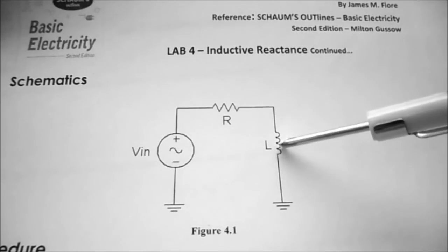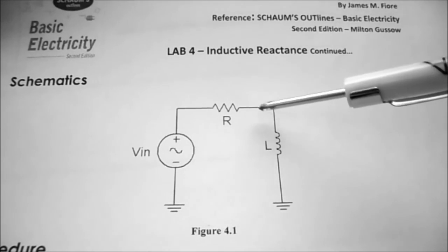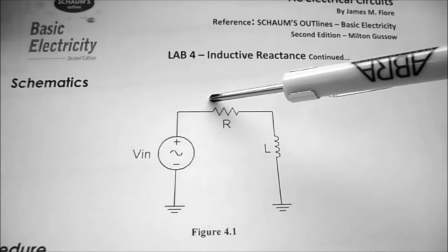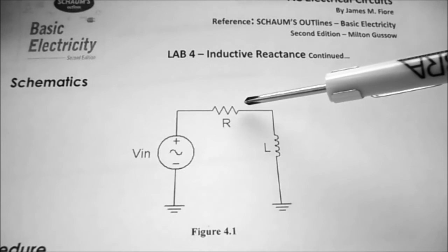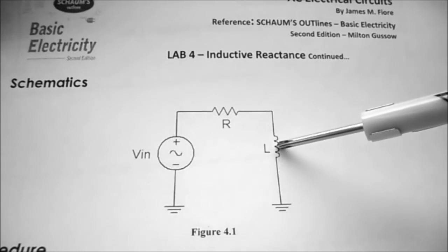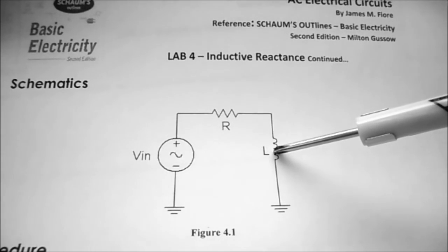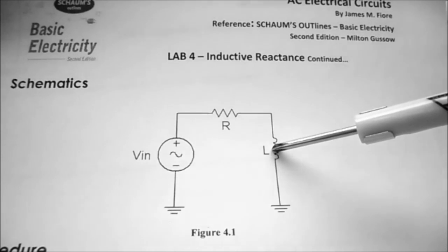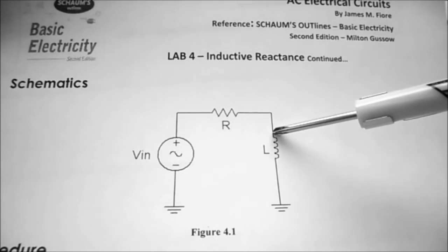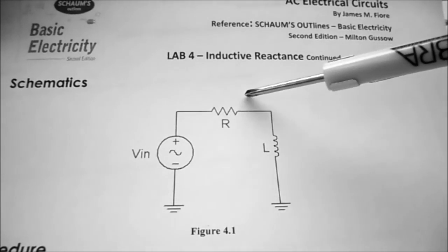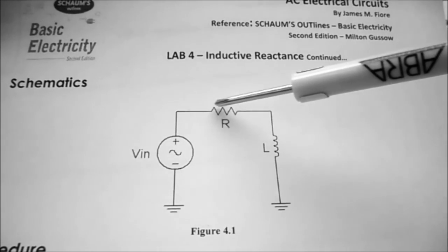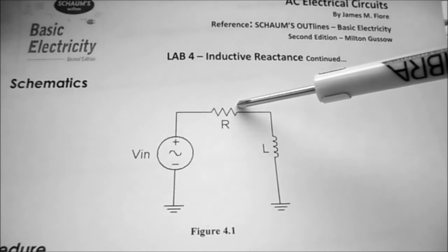So the resistance of the coil has to be compared to the resistor that we used in series, which was 10 k ohms. XL of the inductor is at an angle of 90 degrees. So the resistance of the coil makes no difference to the inductor and is insignificant compared to the 10 k ohm resistor we used in our circuit.